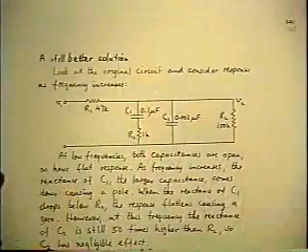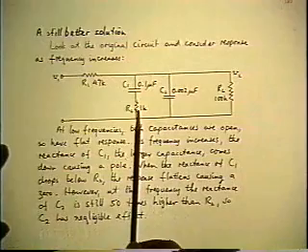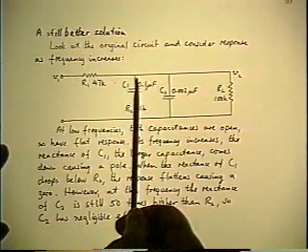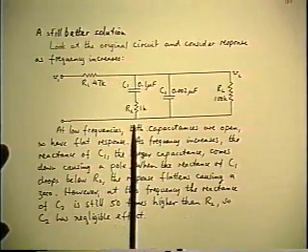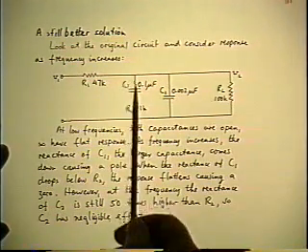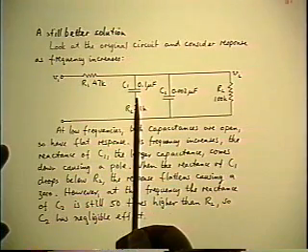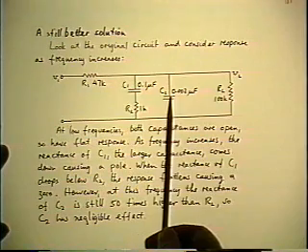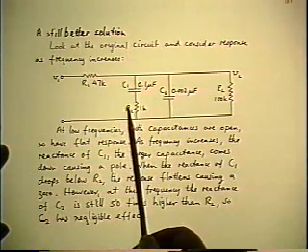The next thing that happens is the reactance of C1 comes down until it approaches 1K, in which case the total impedance of that branch starts to level off at 1K as the reactance of C1 drops below it. The reactance of C2 is still 50K, so it's still negligible. So as the reactance of C1 comes down, that slope in the gain will level off. That's a 0, a concave upwards corner. Again, dominated by C1 only.